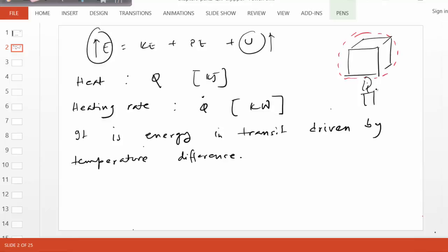So what are the bare bone things we've got to know about heat? You will have a future class called heat transfer just on this concept. First of all, we understand that the energy transfer because of the temperature difference will be higher if the temperature difference is higher between the system and surroundings, which is obvious. If the area of contact is higher. Also, another important factor is the time. If you take longer time, the heat transfer will be higher. And finally, insulation, right? It will depend on how insulated the system is.